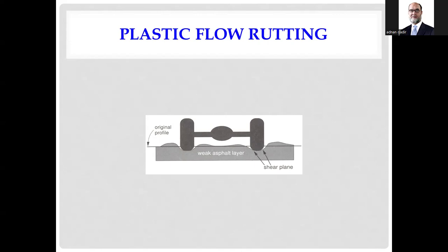So anything that is being used for making the asphalt layer, if your rutting is within the asphalt layer, then you have to remove that asphalt layer. There is nothing. No overlay of 2 inch will make this good. You have to remove this layer, throw it somewhere else, or sometimes you can use it as recycled material, but you have to relay this asphaltic layer. That's the only solution. The solution of rutting is to remove the layers.